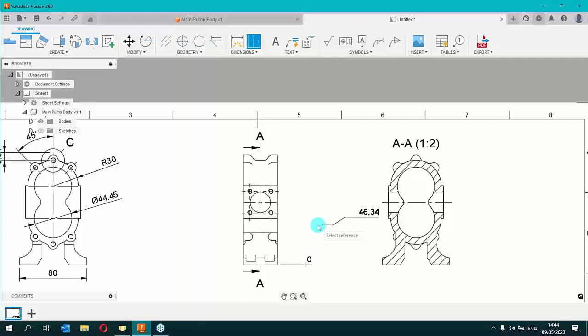So for those who are hoping to work with sheet metal parts, this is a very handy tool to have, specifically if you're going for flat pattern parts as well, because it enables the machinist to program the machine on how to drill holes exactly and to create the features that you specifically need. So with the help of this, even if you hover over the model, you can specify specific regions from where you want the coordinate system to be built up.